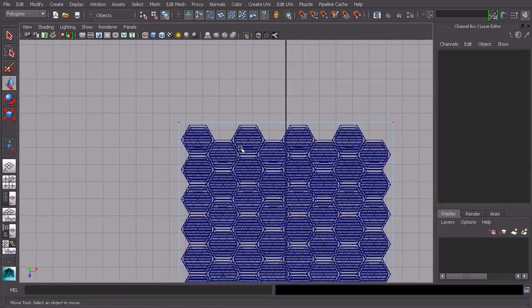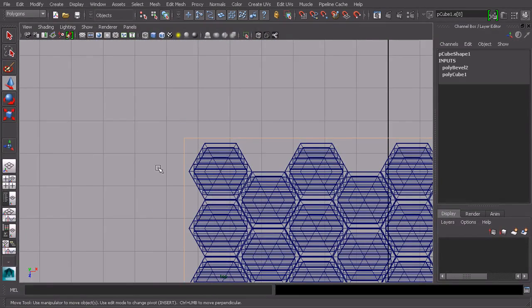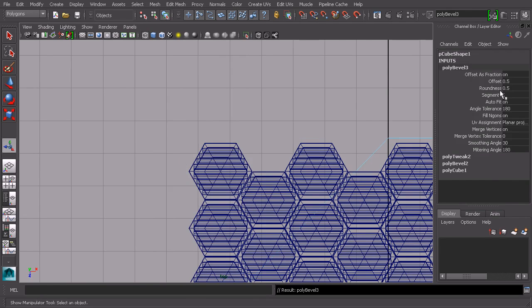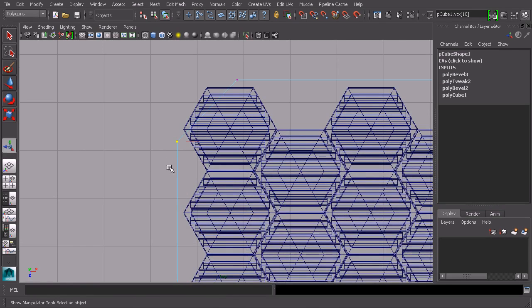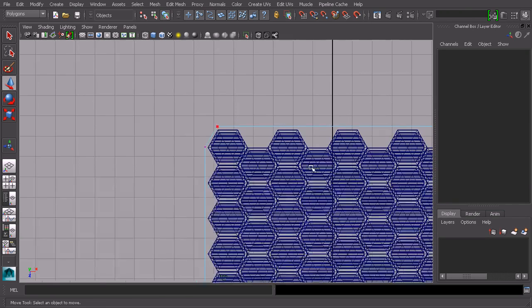Okay, we can sort of do the same thing maybe over here. So I'm just going to select this edge. Now just drag across it so I know that all those edges are selected. Now if I deselect these and these, I know that only that edge facing away from me is selected. So just that corner edge you can see here. So we'll go ahead and again bevel, bring that offset amount back, and we just want to add it in, and then we can get a little bit more control over it. And I just want to move it in a particular axis, so I don't want to move it off. So just using the Z-axis here, and then here we'll use the X-axis to bring this over, just so it matches up with the edges of that.